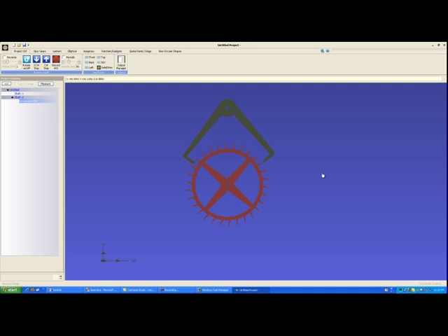So here we have our escapement, and if we hit rotate, we can see that we have a simulation of the rotation. The speed at the top of the screen will allow us to speed this up quite a bit so that you could see your second and minute and hour hands move in case you had a clock. It is not representative of real time. No matter what pendulum you put on, it will always swing at the same rate because it's not a real time thing. What I tend to do is to move it up manually until it's swinging approximately at the time that the pendulum dictates, and then I have an idea what my clock is going to look and sound like.